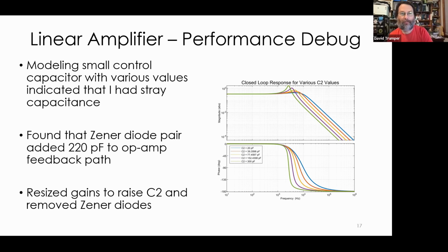And I have to admit, I was really surprised by how large the stray capacitance of these Zeners is. But it's in the data sheet when you look for it. This is the kind of thing where, when you do experimental work, you have to have your eyes open for things that weren't in your model. The world doesn't know what your model was, and it's doing whatever it does. So you better have sufficient humbleness to go looking for where something came from.